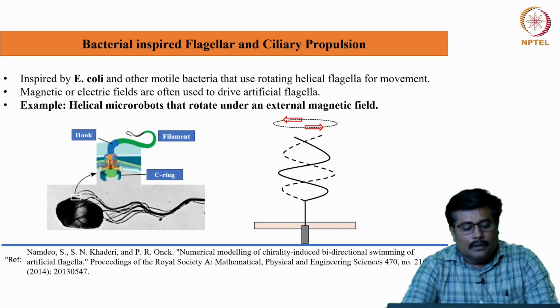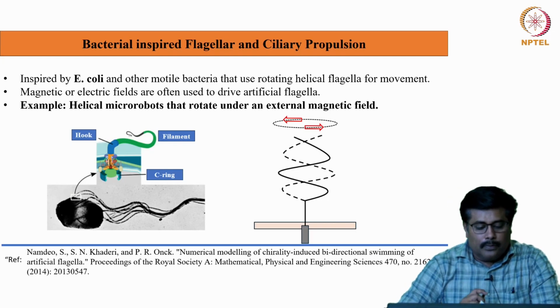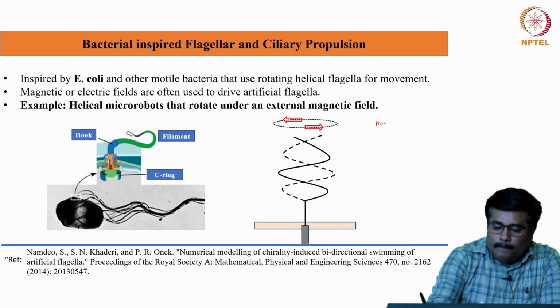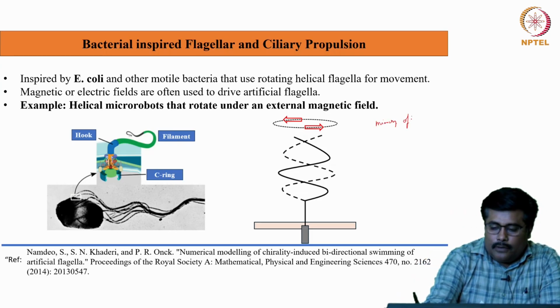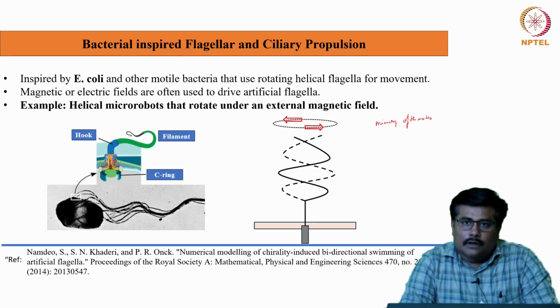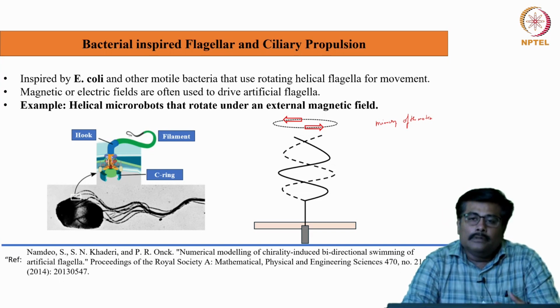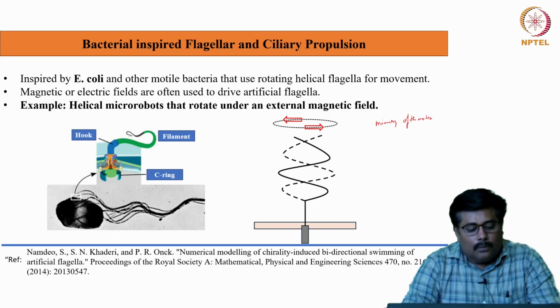Apart from that, the domination of viscous force highlights the requirement of non-reciprocal motion for a Newtonian fluid. So when we talk about mimicry of motion, the first mimicry from a micro robotic point of view is the bacteria flagella, the sperm flagella, the cilia and fish, which have shown a promising solution to control micro robots in the low Reynolds number flow regime.